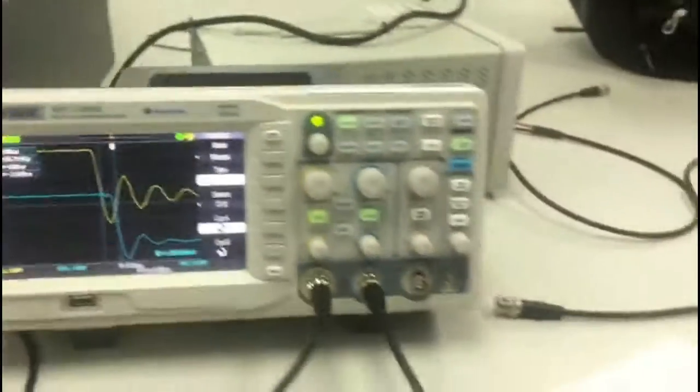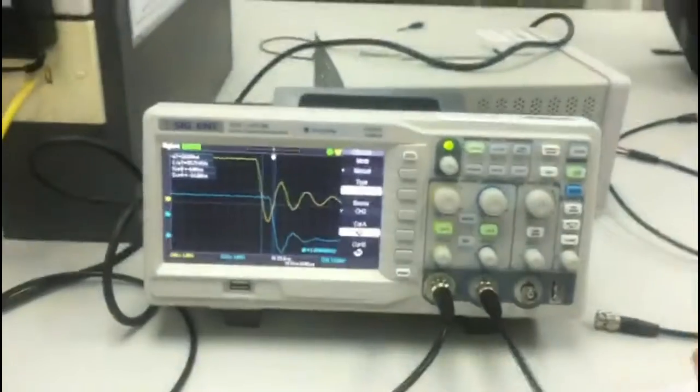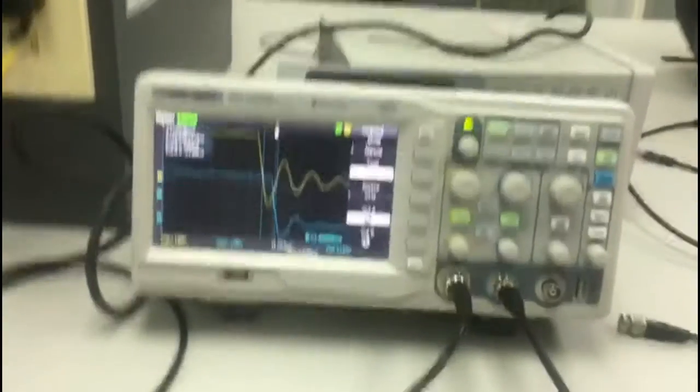And oh yeah, you need to divide by 4, as I just explained, because this is 4 NAND gates. In order to find one NAND gate, TPHL needs to be divided by 4 and then you get the actual TPHL for one NAND gate. Yeah, that's all.